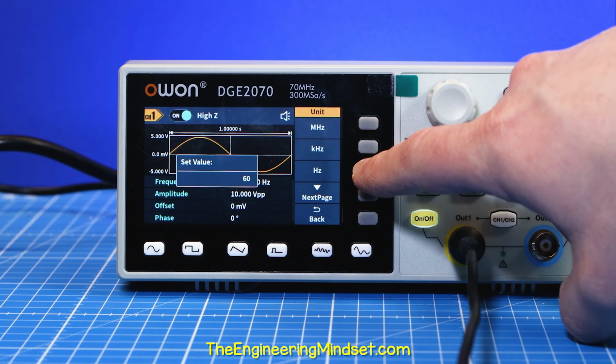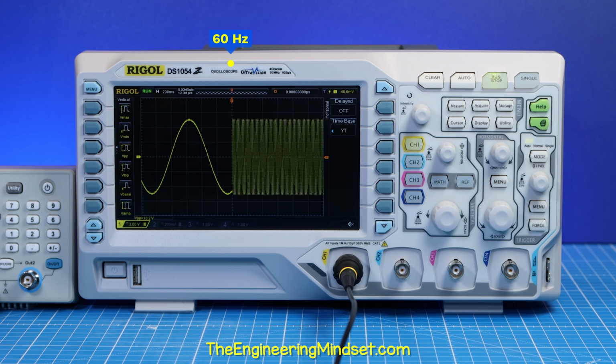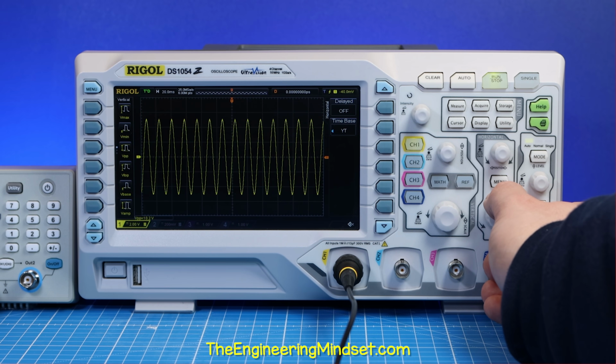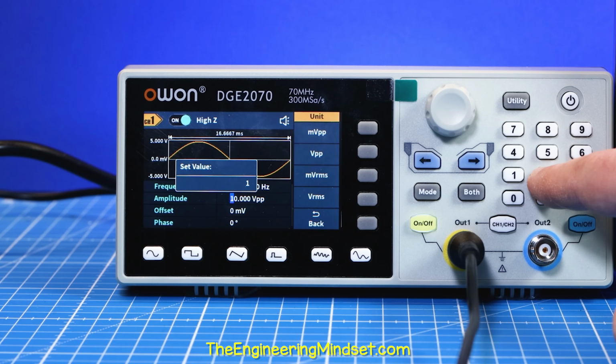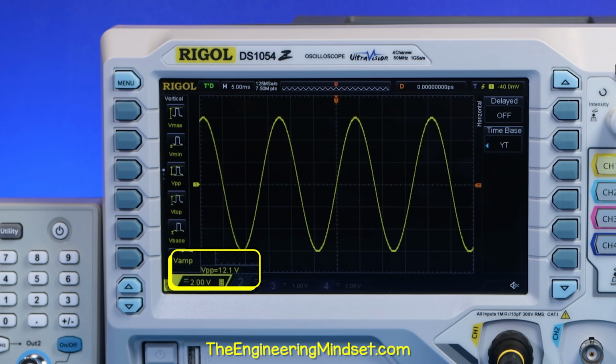Now change your signal generator to 60 Hz. Notice the screen will fill up because there's now more cycles being displayed per second. Adjust your scale to around 5 milliseconds to see it clearly. Now increase the voltage to 12 volts and see how that changes on screen.